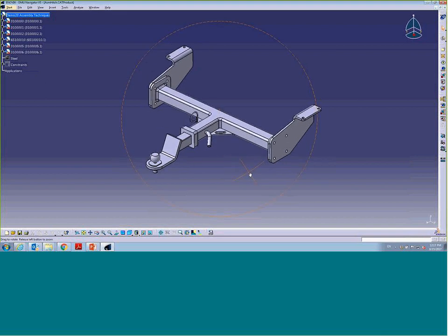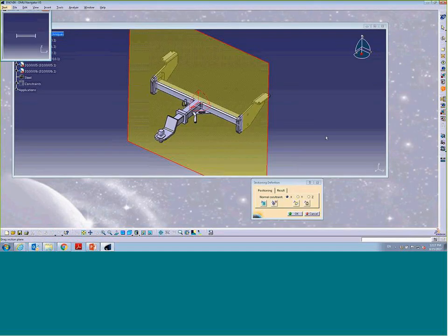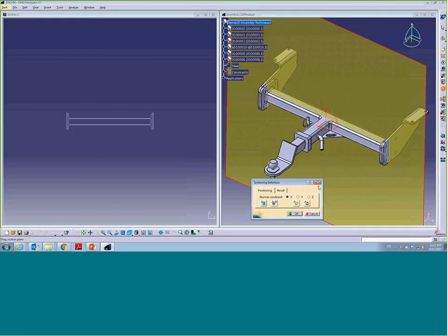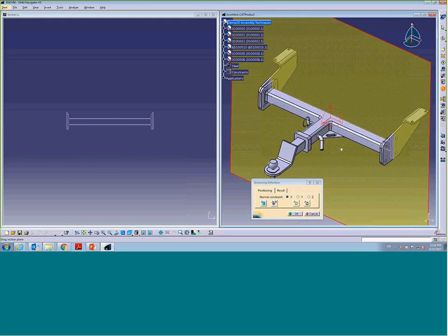We want to do perhaps a cross-section. Okay. Tool for creating a cross-section. I'm going to section, and it shows me a couple of windows. I'm going to tile them, tile vertically. So the actual cross-section, and that's the plane. So you move the cutting plane, the cross-section plane. You notice on the left side it changes. Okay, we can take the plane, etc.